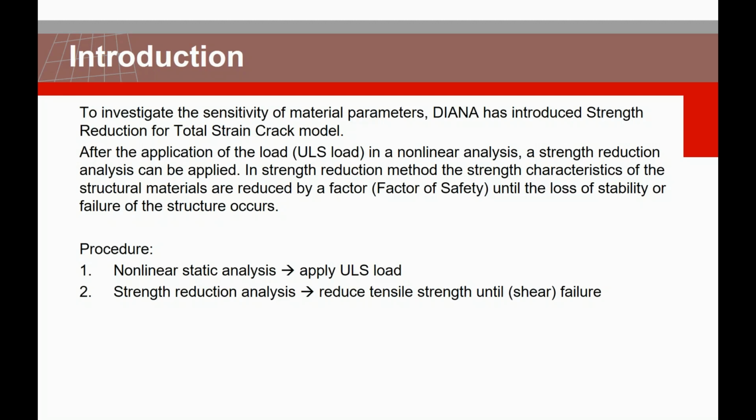So what we do, I will explain it later in the live demo. We will actually do a sort of investigation on the sensitivity of, in this case, the tensile strength. And we use the new feature, strength reduction for total strain crack models for this. To do that, we first have to apply a certain load, let's call it the ULS load, in a nonlinear analysis. And subsequently, then a strength reduction analysis can be applied.